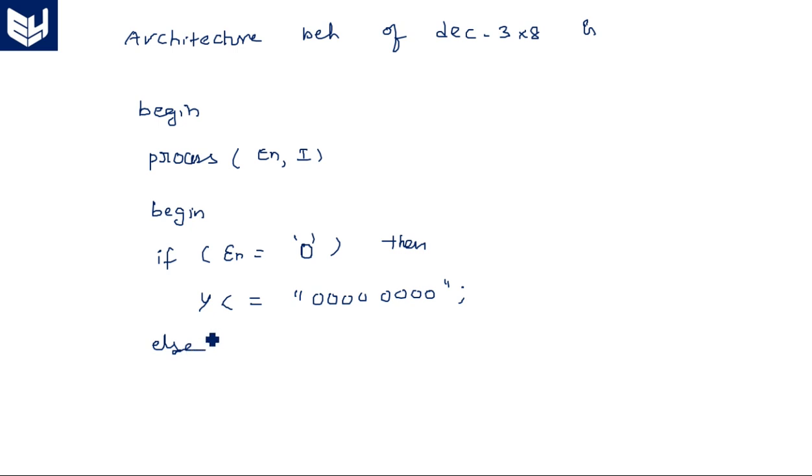now we have to go for the conditional statements. The conditional statements we write here are case and when. The output varies depending on I, so case I is when triple zero implies y assigned with what? I means I2, I1, I0. So 000 has the equivalent decimal number 0. So the y0 pin is activated and the rest are zeros: 0 0 0 0 0 0 0 1; semicolon. This is the first line of the program.